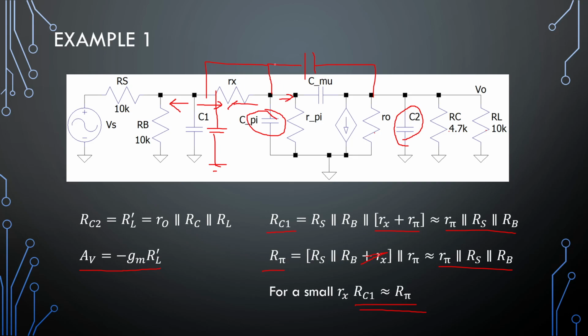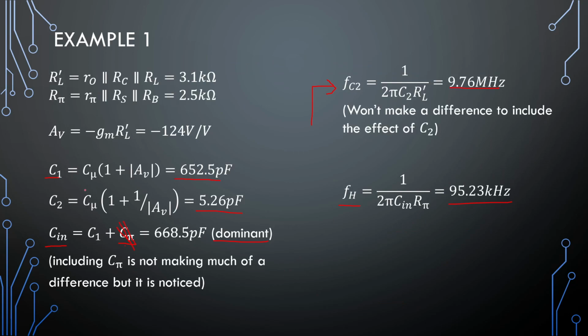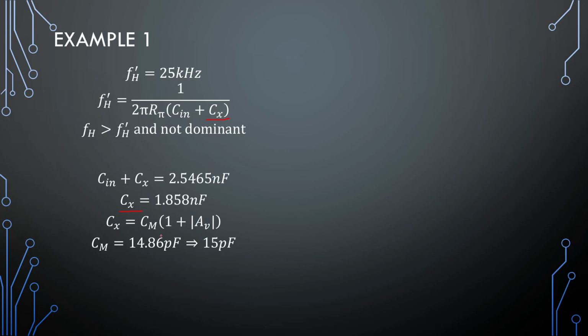It needs to be moved to the right position to be a Miller capacitor and something useful when we build it. Okay, and how we did Miller is we took our Cμ and we multiplied it with a gain plus 1. Now we're just going to reverse this effect for ourselves.